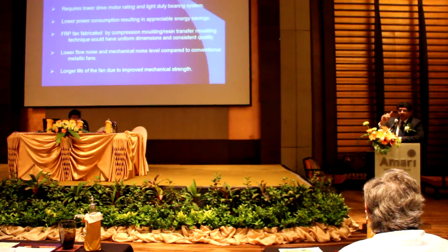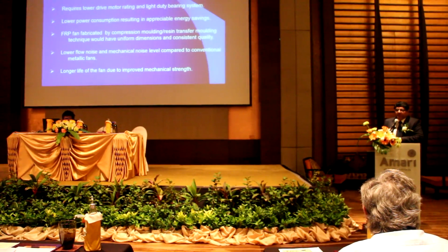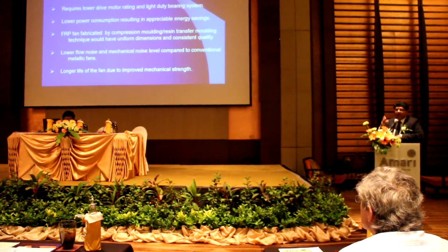But it is the operating torque, which we are talking of in terms of operating power, which is basically because of the superior aerodynamic design that there is an energy conservation possible. The general thought is, oh, the blades are lighter and so there is an energy saving. No, that's what I just want to clarify in case some of you had thought this.